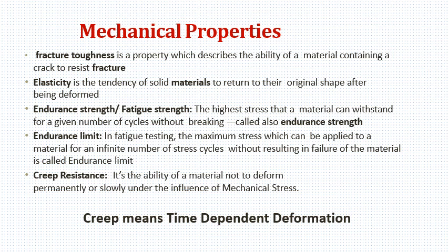Next, endurance strength or fatigue strength. It is the stress that a material can withstand for a given number of cycles without breaking. For example, if we give a fatigue load cyclically, again and again, the material withstands a number of cycles. Next, endurance limit.